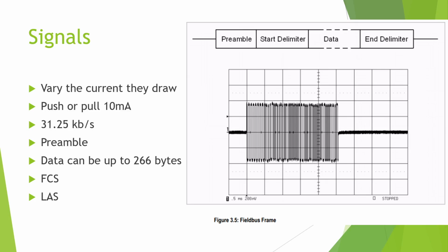It could be time-based. Okay, we're going to send a 5 millisecond preamble out first. You don't want to send too much preamble. Why? Exactly. If I send out 1 minute's worth of preamble before I send every message out, there's now 1 minute of no data that I can send. So you want enough preamble to get everything synchronized, but you don't want too much. I'm assuming you don't get to choose how much preamble you have. I think it's just set, but it is going to be there to help get everyone synchronized and things like that.